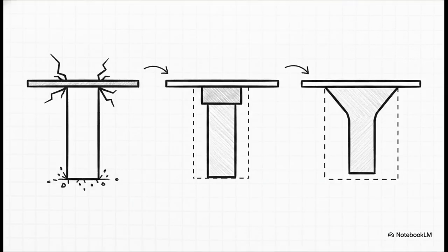And mapping out critical shear sections in flat slabs is just as rigorous. Engineers have to do this to prevent what's called punching shear failure. That is a catastrophic event where a column literally just punches right up through a flat slab. The critical section calculation completely shifts depending on the exact architecture, like whether your flat slab has drops or if your supporting column has a flared column head. The code leaves absolutely zero room for guesswork here.